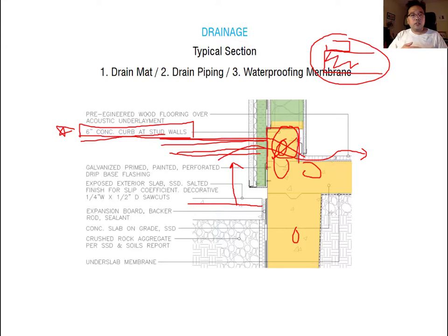And then we're adding the insulation. You remember the exterior insulation with the reinforced rain screen system, and then we're also adding the same interior insulation here, to meet the minimum R-value. And then you have to protect against water. So simply you can add the waterproofing membrane and then a vapor barrier inside, and then waterproofing all around here. Okay, just protecting your structure and foundation. And then simply adding the finish wall and finish floor.